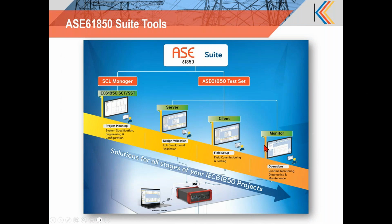So with test set, you will be able to do client, server, and monitoring mode. Monitoring mode is a special mode where you listen to the traffic, mainly connecting to the mirror port of the switch in the substation, and you can essentially view everything from that mode. That will give you a lot of capabilities from a monitoring and troubleshooting perspective.